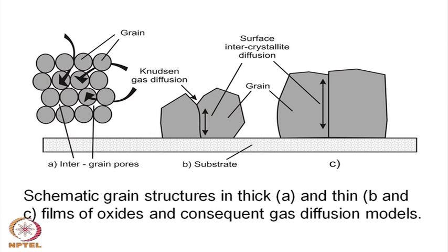So, this is one kind of surface, where the surface is exposed to the atmospheric gas. But here is also another surface, internal to the material, and this is also a crystallographic discontinuity, and gas can diffuse in. So there are two different surfaces: one is the external surface and the other is called the internal surface. In both these cases one can have a role to play so far as the conductivity, or the conduction mechanism, is concerned.